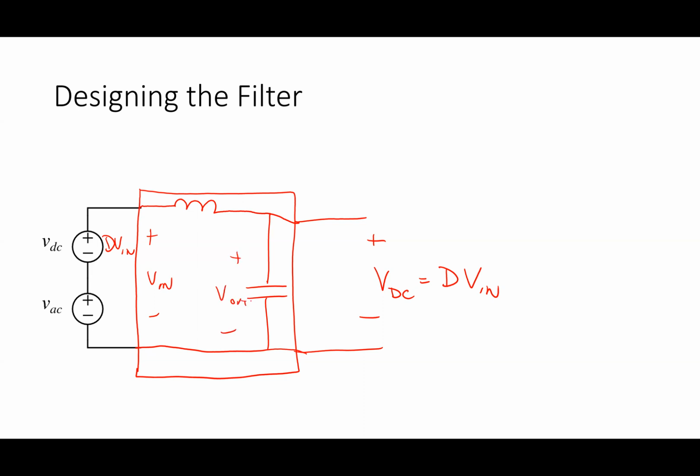I want to check to see that's a low pass filter. And I want to do that in a simple way. How could I check that? Yeah, so let's check the impedances. Let's say I'm at a low frequency, like DC. At DC, what's the impedance of the capacitor? So first of all, Z sub C is what, and Z sub L is what? Yeah, 1 over J omega C and J omega L.